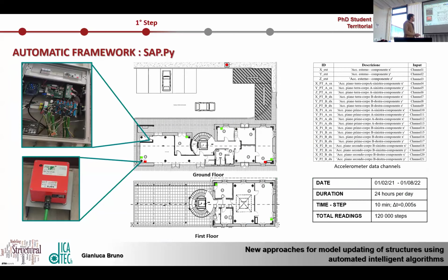This building has been subjected to a monitoring campaign since 2022, with two triaxial accelerometers on the ground floor and six biaxial accelerometers on the first floor. In particular, they record a signal of 10 minutes every half hour with a frequency of 200 Hertz.